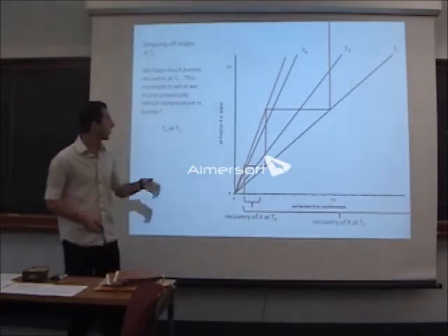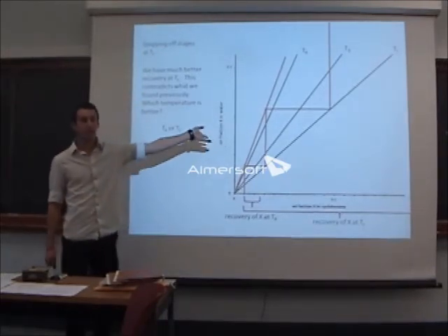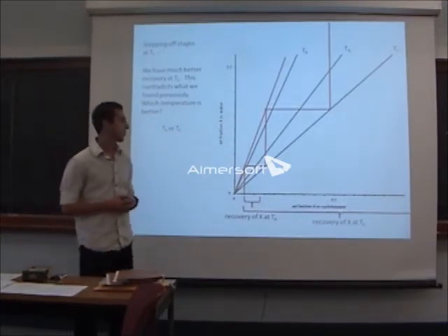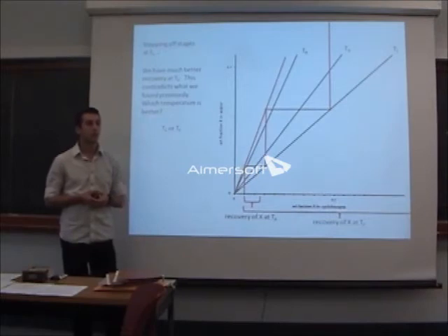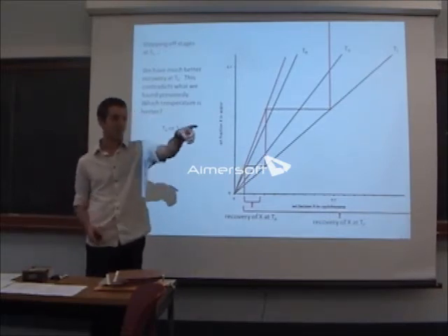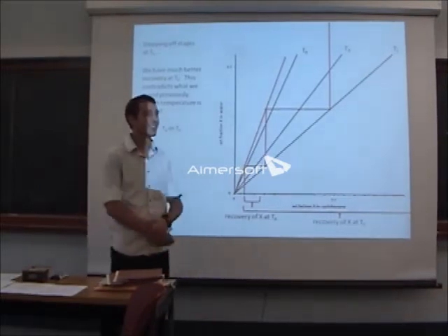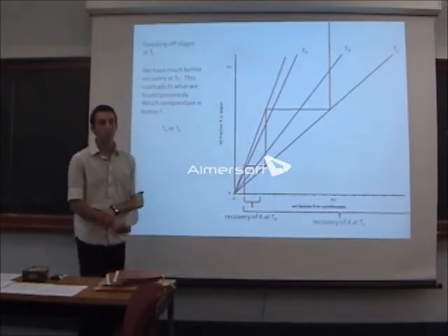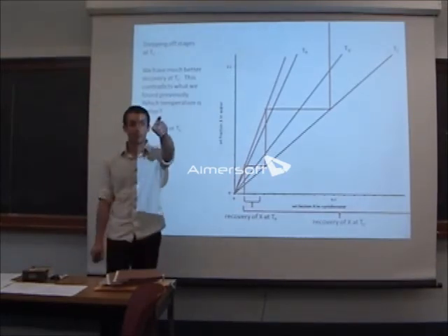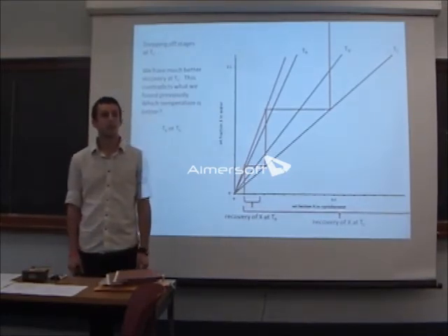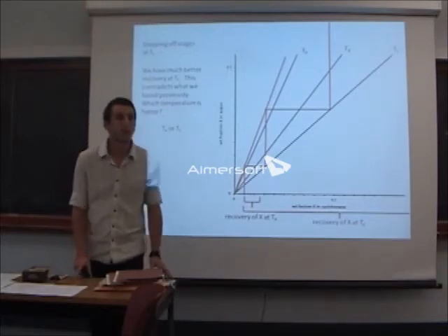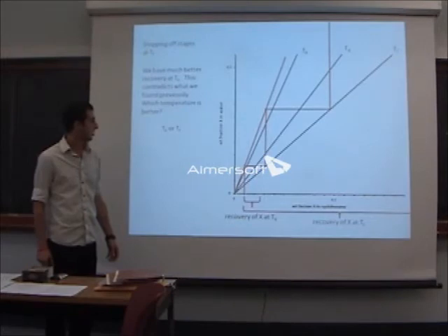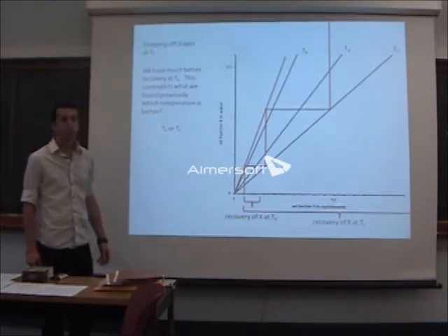Okay, so that means something about this was wrong, right? What did I do wrong in this example? Operating line? What's wrong about the operating line? I'm not really sure, but there's got to be something wrong with the operating line. Well, shouldn't the operating line be different if it's at a different temperature? No, it's not going to be different for different temperatures. Rachel? For the operating line, you start with no X at all. Like your weight fraction in both of the streams, you start at 0, which means there's no X in either stream.